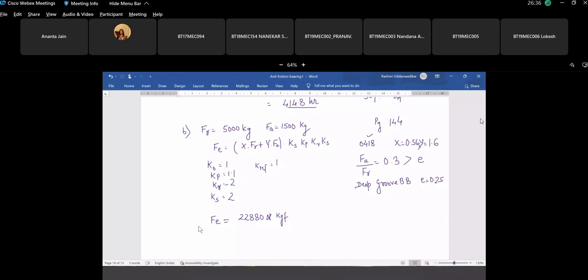And if the bearing is same, so the value of C, the dynamic load carrying capacity, is same. Let us convert this into kilonewtons, because C we know is 146 kilonewtons. So you convert this also in kilonewtons to 28, assuming